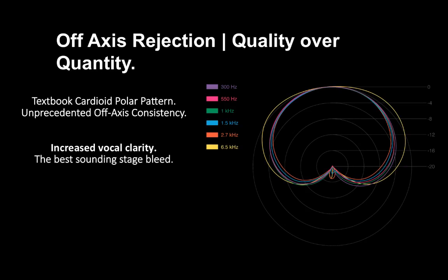And then we also wanted to make the best sounding cardioid mic we've ever done, because we had every opportunity to do that in the process. We could tweak and tweak and tweak. The polar pattern defines how that microphone picks up sound at what angle, right? So cardioid is a very, very common polar pattern, a unidirectional polar pattern. And it picks up sound from the front and rejects the most from the rear.